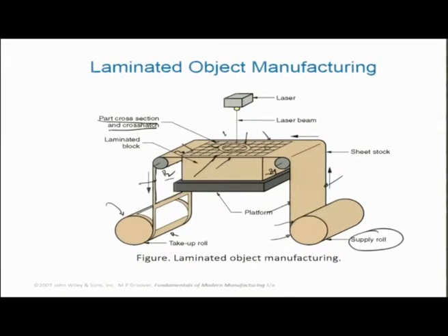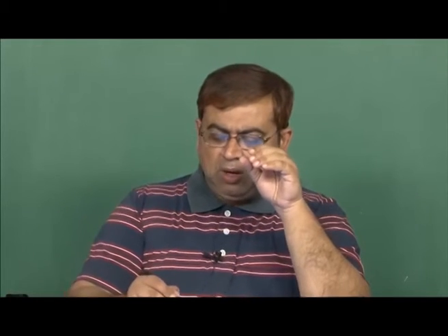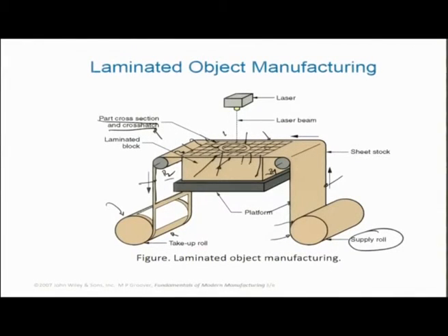The idea is that later on the cross hatching is typically done because we want to remove these portions out easily, so that the part which is actually not cross hatched remains back. This cross hatching probably is at a level or a dimension where a slight amount of effort releases these very easily, okay, because they are smaller in size in comparison to the overall part size. And so the idea here is that these all are blocks which are being formulated with the part, and these blocks are getting lost, okay, while supporting the part as the part is getting built up three-dimensionally.